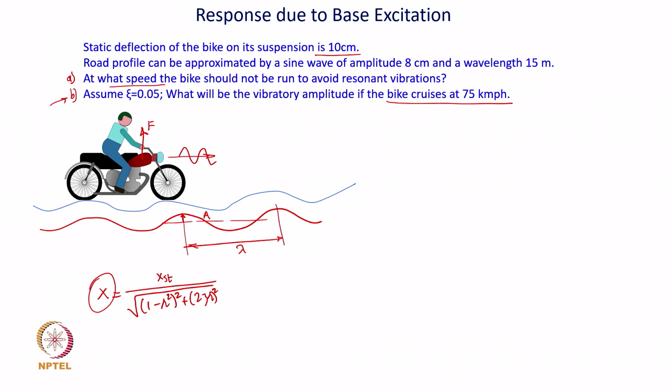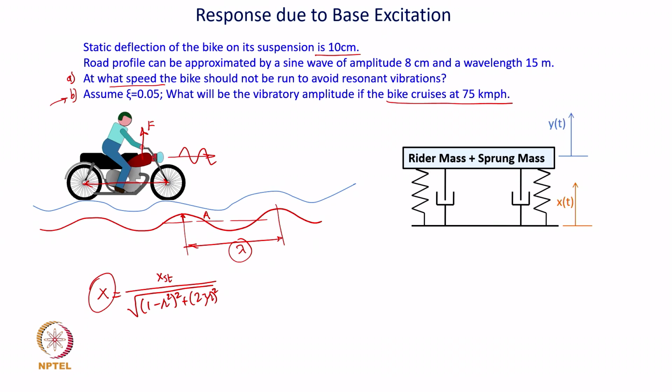What it says is, this physical system you convert it into a simplified vibratory model. Now, we assume that this wavelength is large enough compared to the distance between these two wheels. So, we model this entire system as a simple single degree of freedom system with a single mass, single stiffness and a single damping. So, this is how I will model this system as this, which itself can be further simplified by a simple single spring, single mass and single dashpot